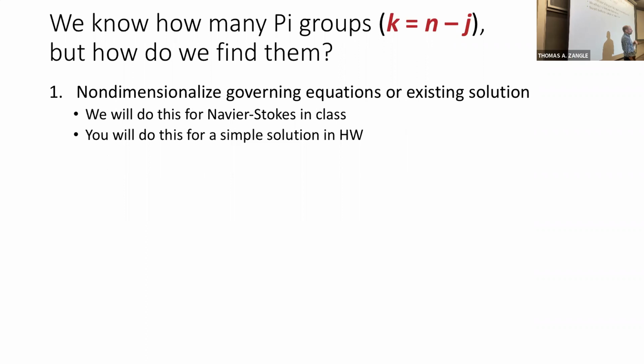And we could divide through, for example, by g or one of the variables within that equation. Every term still has the same dimensions, but now we've changed those dimensions a little bit. So you can carry that same idea through of dividing through by different constant terms to take an equation and turn it into a non-dimensional form where every term has no dimensions. And that's basically what this approach is.